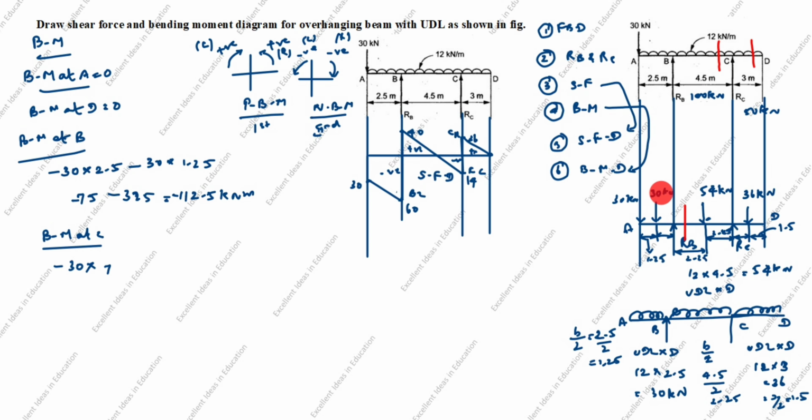Next, you see this 4, the arrow comes down from here to here is anti-clockwise. You see anti-clockwise is negative. 30 into perpendicular distances from here to here. This is 4.5. This portion is 1.25. It comes 5.75.